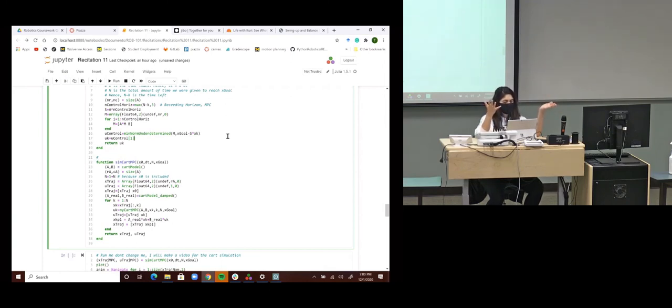And then, depending on your control horizon, it can be anything. Let's say I choose it to be 20, so 2 seconds. I'm going to look 2 seconds in the future, and I'm going to try to get to my goal in those 2 seconds. And this should be my control sequence for those 2 seconds. Then I take the first control. I get the full sequence of controls, I know everything that I'm going to do for the whole 2 seconds, but instead of doing everything for the 2 seconds, I just find out what am I doing at this instant? So I just get the first control. So at this instant, I'm doing this.